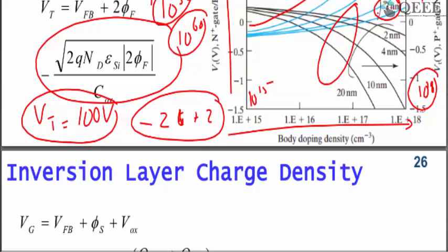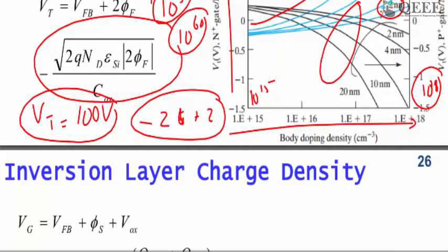Suppose you shine light, a photon can generate an electron-hole pair. Similarly, if you increase the temperature, electron and hole pairs can generate. Similarly, they can recombine also. They can recombine radiatively, that means an electron and hole can recombine and emit a photon. That is what happens in an LED. But silicon is an indirect band gap semiconductor, so the efficiency of that process, the electron and hole recombining and emitting a photon, is very, very small because of the momentum conservation involved.